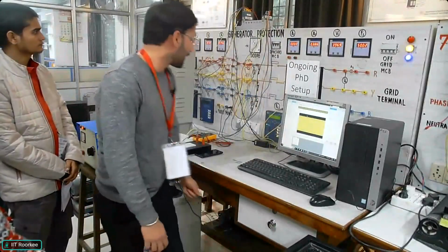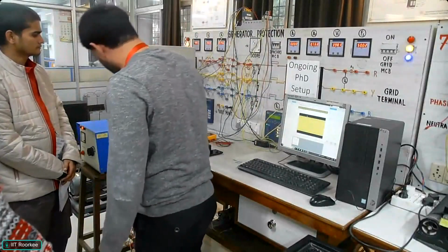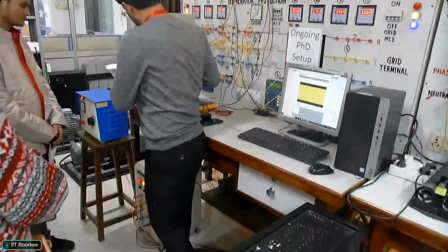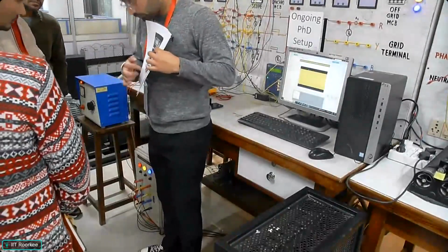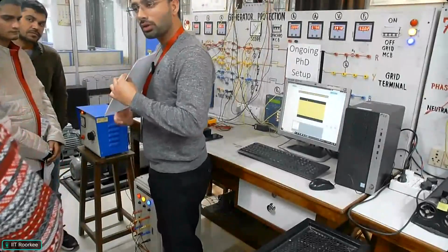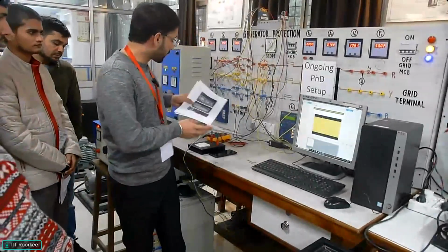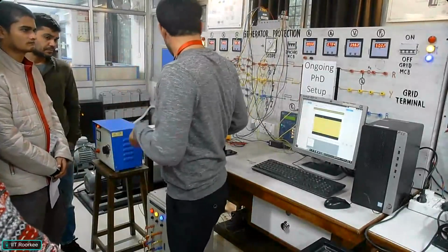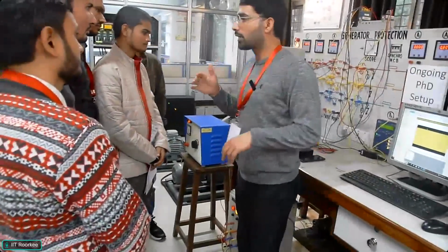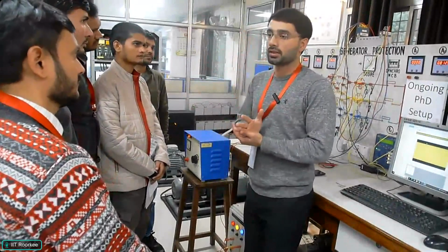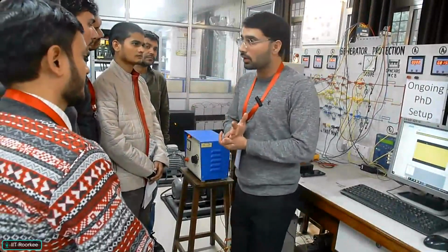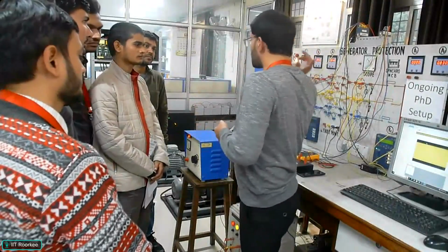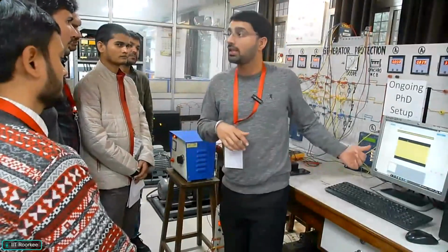Now for any further analysis for any fault, what I have done, I have taken 2 connections from the rotor terminals. We have 4 rotor terminals here. So I've taken any two out. And for that purpose, those connections I'll switch off. And what will happen, the excitation supply will cut. When excitation supply will cut or any fault will occur in rotor terminals, the terminal voltage will get affected.